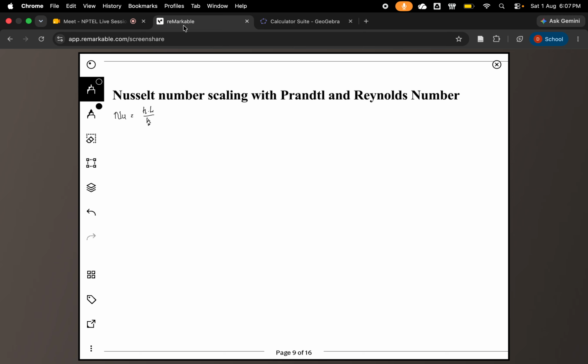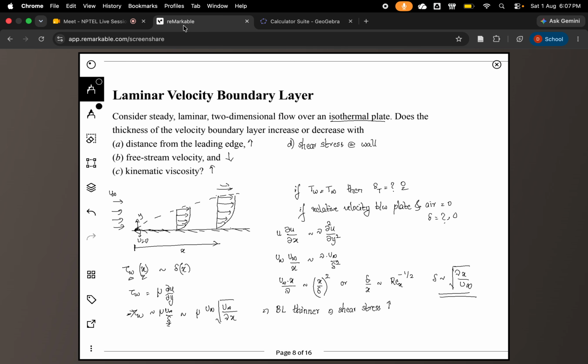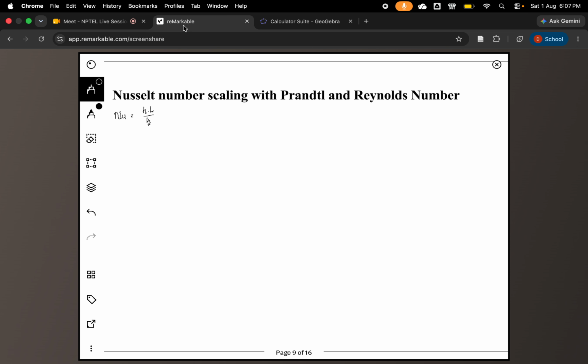Okay, so one more point. What is the characteristic length we will use for this flat plate is the length along the flow direction. So why aren't we using the length along the other direction? That is also something maybe we'll discuss a little later. But for now, let's say that this length is the length along the flow direction that we are considering. The characteristic length is along the flow direction. This is for external flows. When we move to internal flows, then again this characteristic length definition will change. So depending on the problem, this changes. How do you decide which characteristic length to use is again something that we will discuss a little while later.